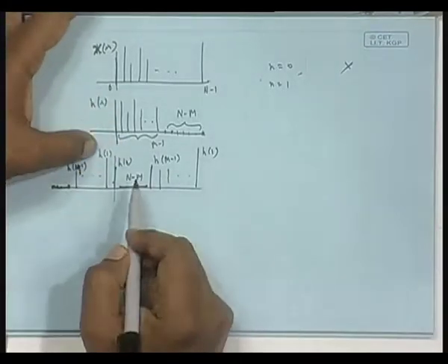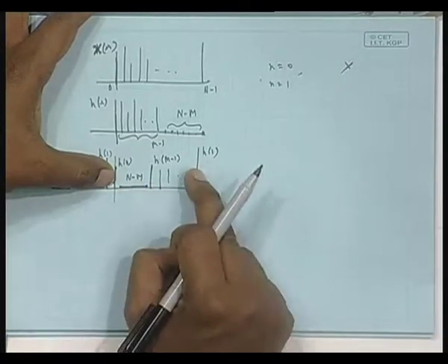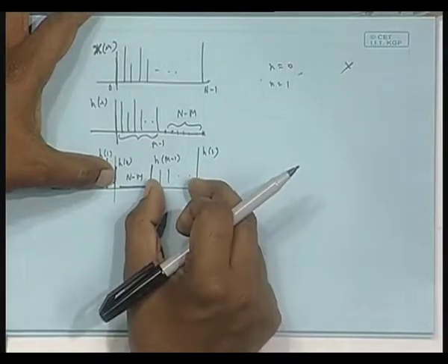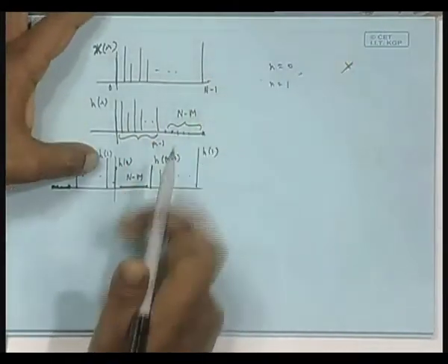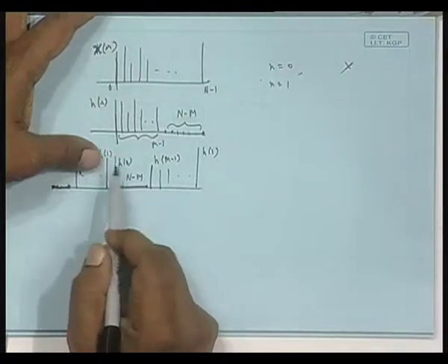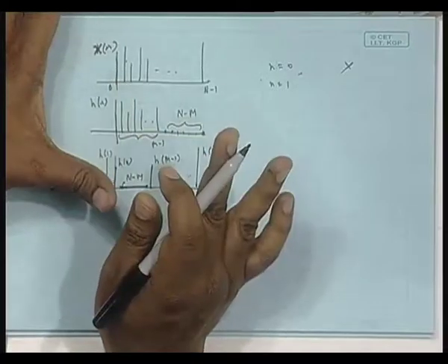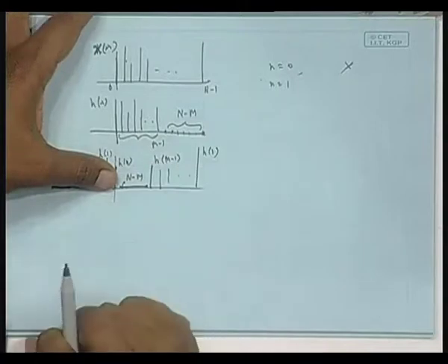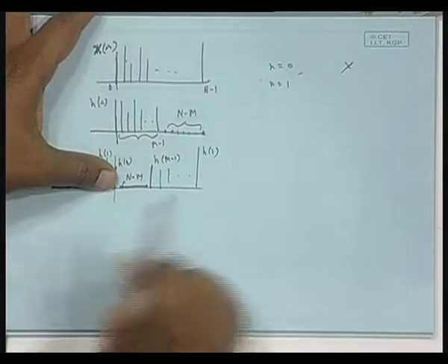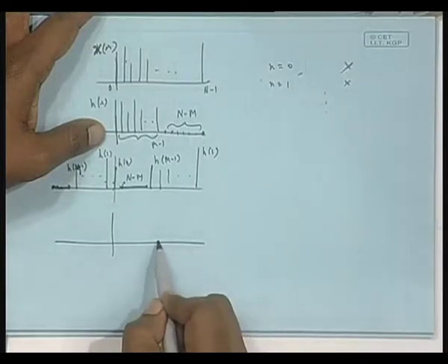Okay. At n equal to 1, these 2 will move up, this 0, one sample will be moved out, but still these are there, they will multiply with the samples from top and will give rise to error. This left of the 0 pad is fine, h 0 below x 1, h 1 below x 0, that is the linear convolution thing, is it not? But these are creating trouble. So, this will be incorrect, dot dot dot, it will continue till the point where this 0 pad reaches here.